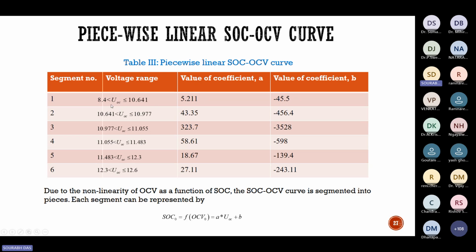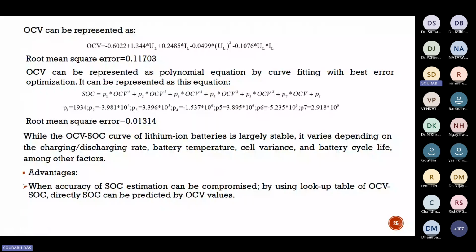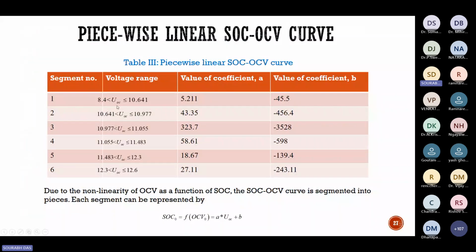If we segment this curve, this figure 23 curve, then we can get this piecewise linear SOC OCV curve, which can give better accuracy for SOC estimation.